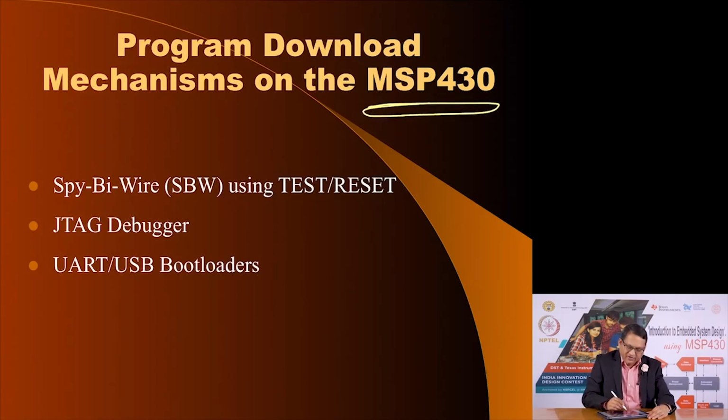You could use the Spy-Bi-Wire method, which uses the test and reset pins on the MSP430 microcontroller, or you could use a JTAG debugger, and you could use the poor man's alternative by using UART USB based bootloaders.